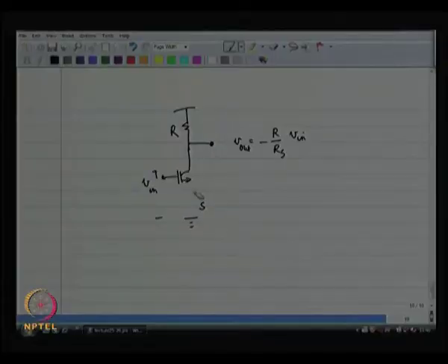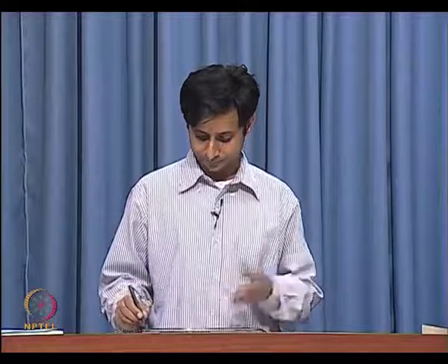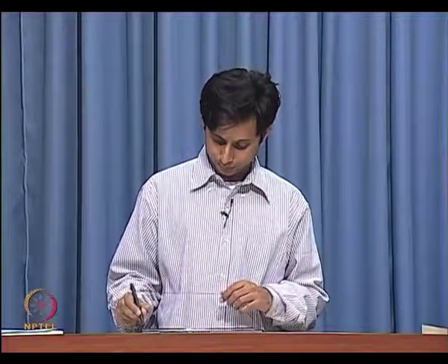You can easily conceive of this, and here this is irrespective of whether the input signal is a large signal or a small signal, right. This is the way we linearize. Now, you could also conceive of putting an inductor over there instead of a resistor. Even that is going to help you in terms of linearization. So, at DC there is going to be nothing, but at the high frequency that will present an impedance, and at that high frequency this is going to behave like a perfectly linear amplifier, right. So, this is the technique we are going to use.